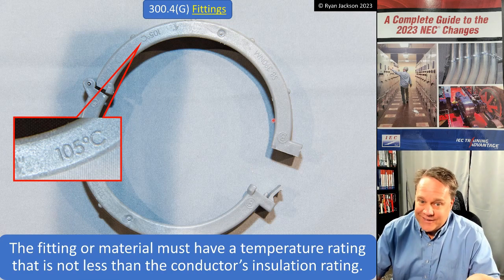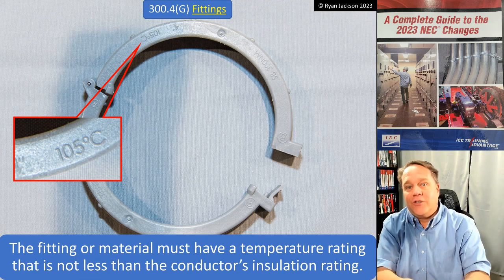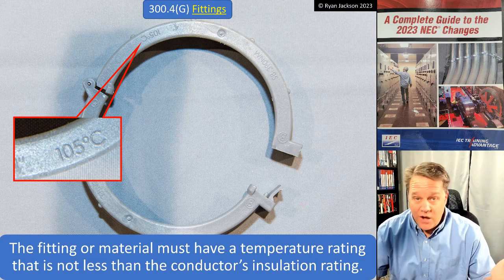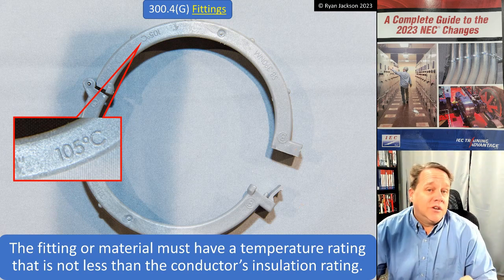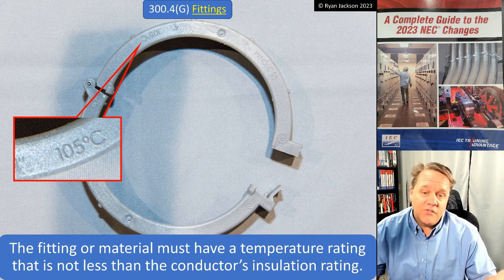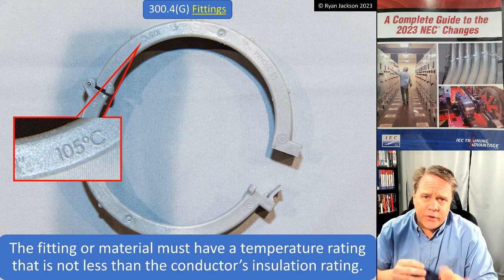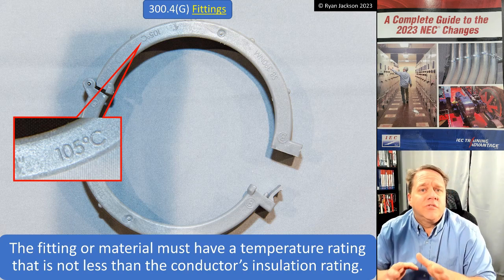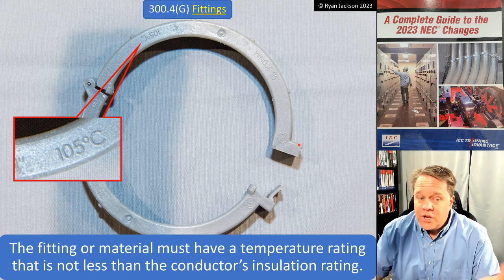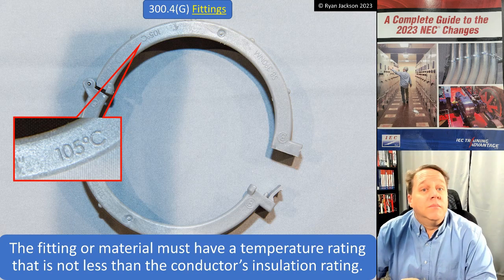It's because it's kind of designed to be installed after the wires are already in place. Is this product a code violation? No, it's not. Is it a code violation to put this on after the wires have been pulled? Yes, it is. And I think you could make that argument in previous versions of the code too. 300.18 says that raceways have to be installed as a complete system before you pull the wires in. Does that include the plastic bushing? In my opinion, yes, and I think it always has. But this section makes it clear now.